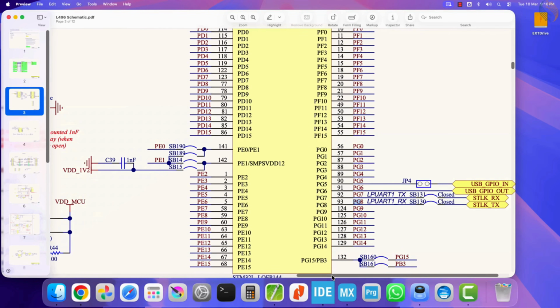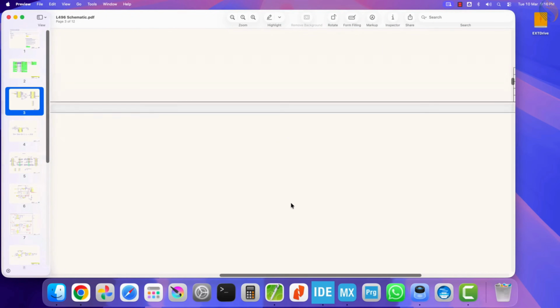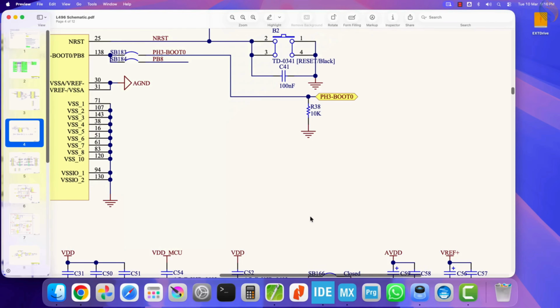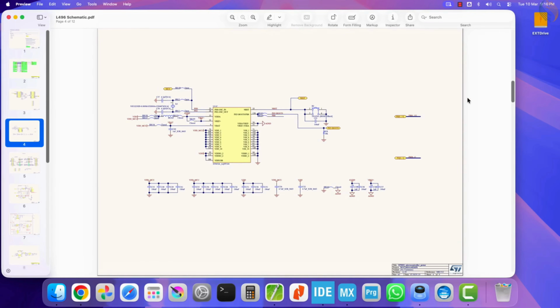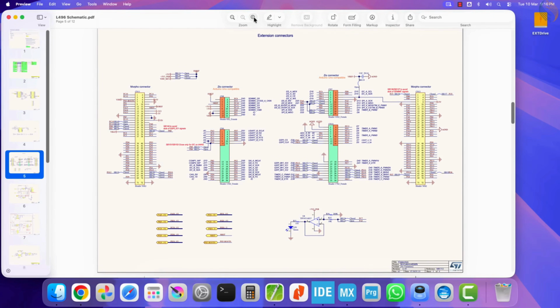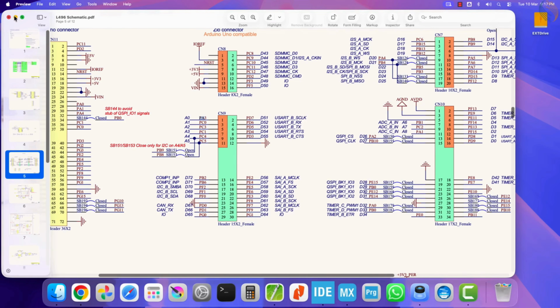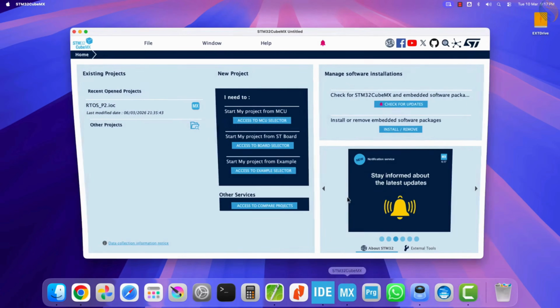the UART in CubeMX. I am also going to use a button to update the data in the structure. The button will be connected between pin PA3 and ground. The pin will be pulled high by default, and when the button is pressed, it will be pulled low to ground, indicating that the button has been pressed. Now let's open CubeMX to configure the project.